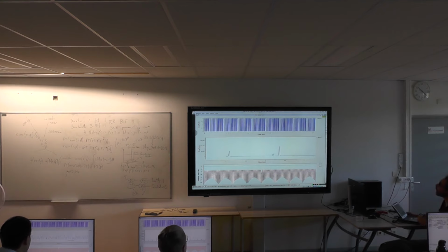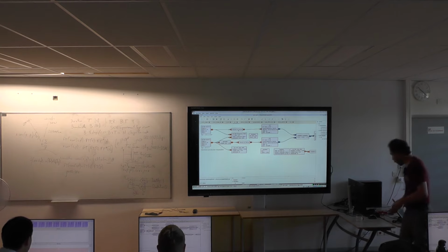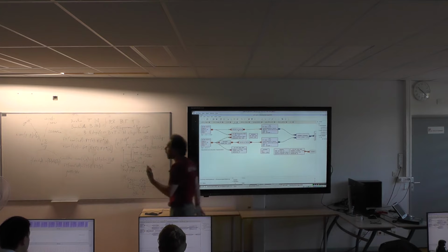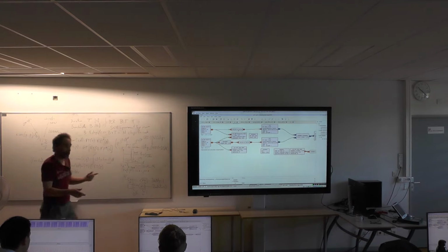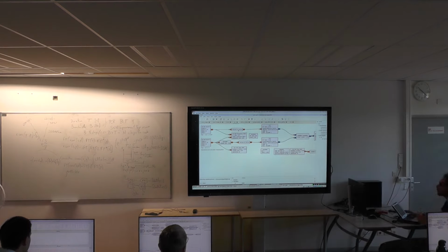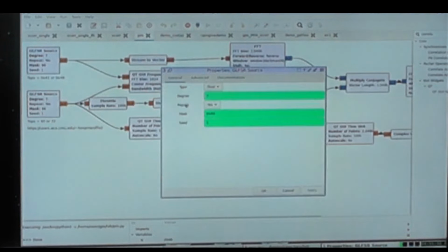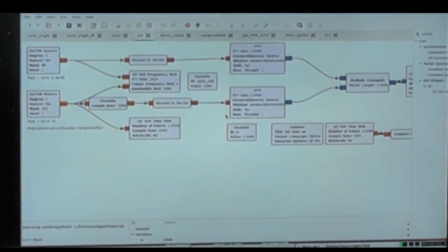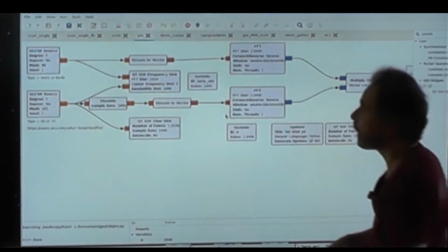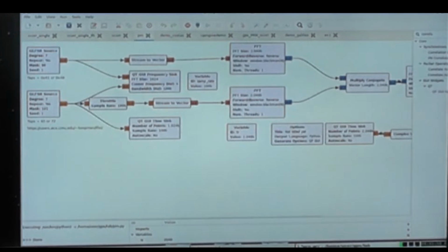So I hope now that you have a better understanding about how we can detect all these satellites. All these satellites are broadcasting a known pattern, and we detect them only by correlating. I haven't shown you yet that we can cross-correlate with a wrong satellite. What we've seen on Professor Koopman's website, for example, is 65, which is another maximum length sequence. But what happens now if I cross-correlate satellite number 60 with code number 65? I generated two maximum length sequences, but now I'm trying to detect the wrong satellite. It's not the one that is broadcasting that I'm detecting.